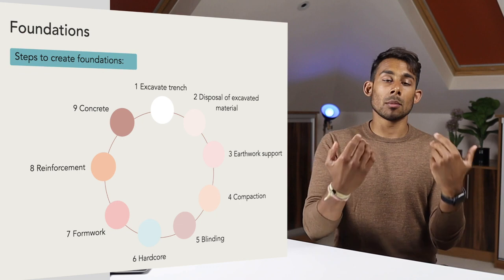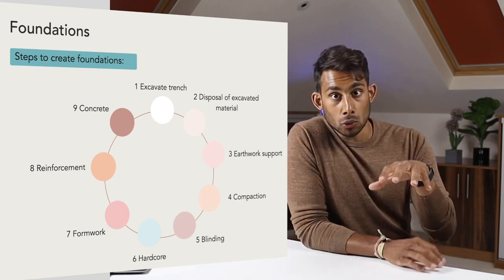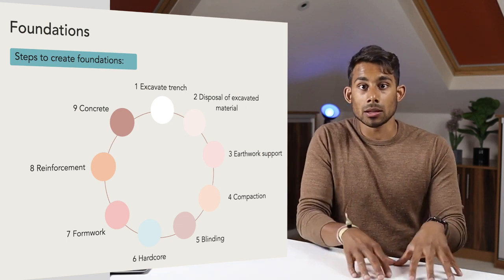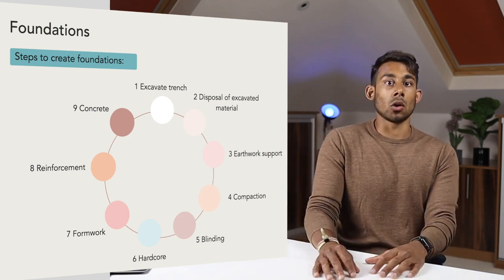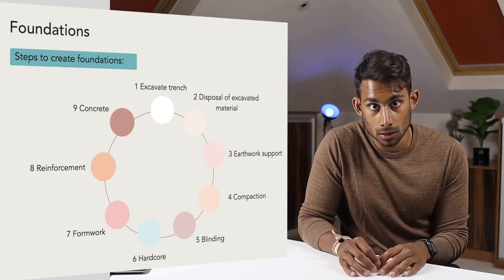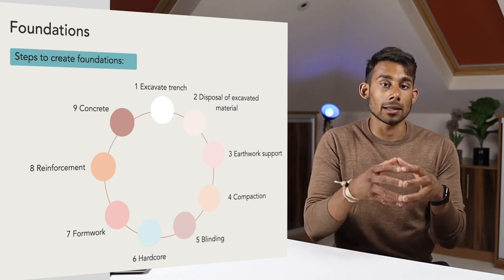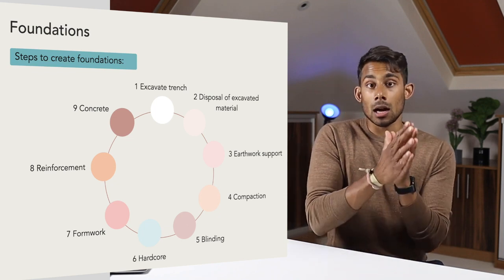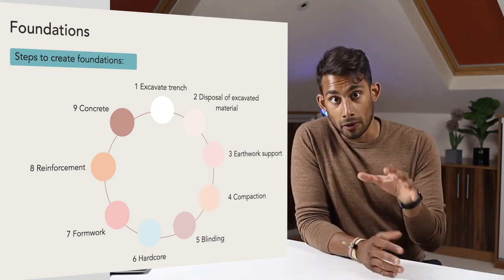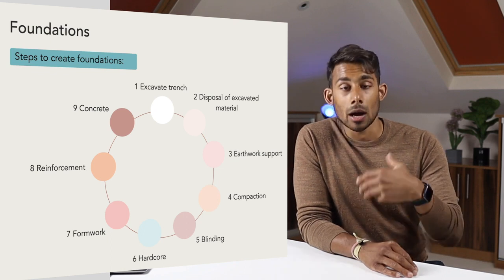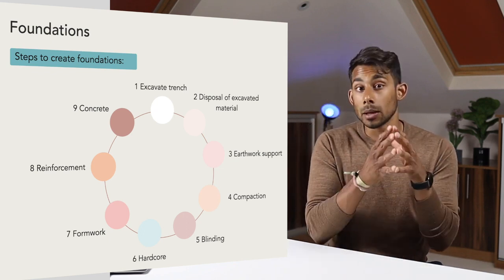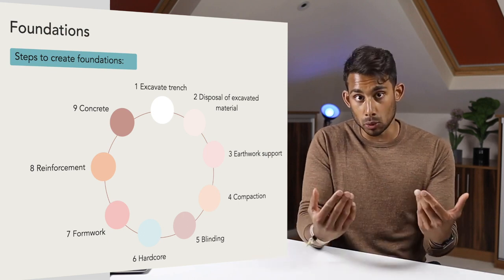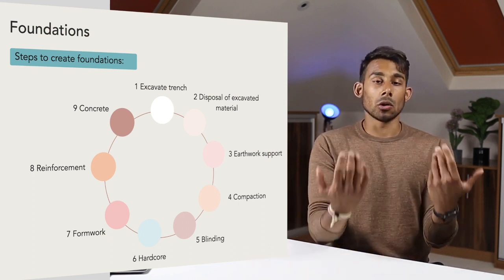The concrete will be reasonably wet when it is poured, so a shovel or rake would be used to roughly level the concrete. A straight edge piece of timber can then be used to tamp down the concrete, eliminating any air pockets. Repeated tamping will create a reasonably smooth surface, but a steel float trowel could be used as the concrete starts to harden for a finer finish. And it is worth noting the smooth concrete can be quite slippery, so often a rough, tamped or brush finish is preferable.